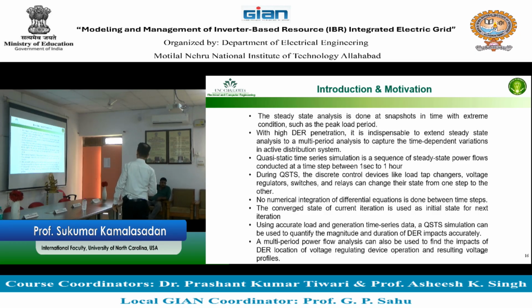During a QSTS, the discrete control devices like tap changers, voltage regulators, switches and relays can change their state from one step to the other. Right? You have a regulator, and it can change its tap from one step to the other. In the time series simulation, you will include those changes. Okay.